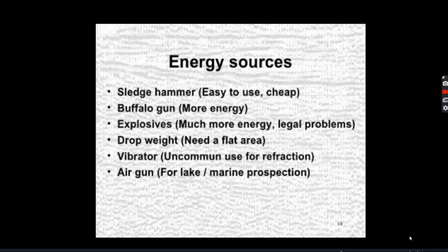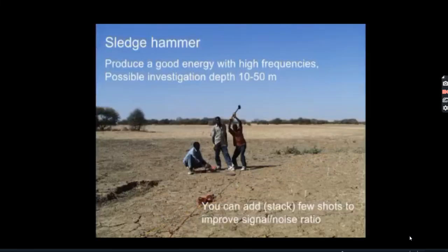Vibrator, uncommon use for refraction. Air gun for lake or marine prospection. Sledgehammer produces good energy with high frequencies, possible investigation depth of 10 to 15 meters. You can add stacking shots to improve the signal-to-noise ratio.